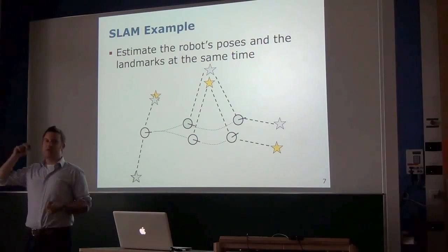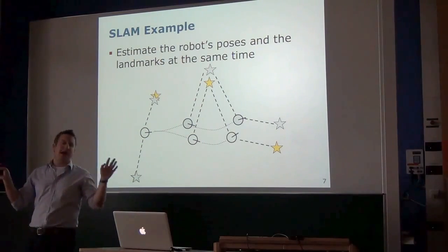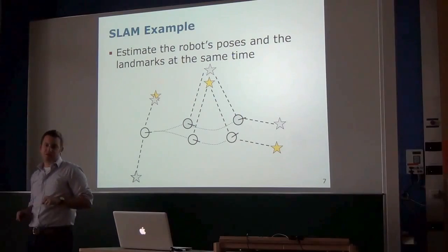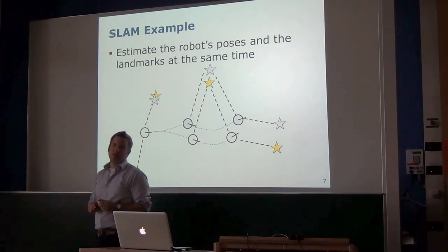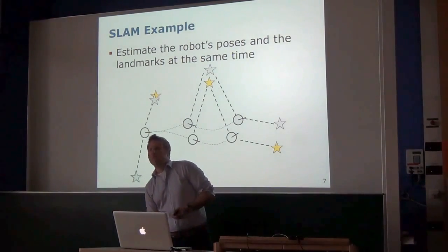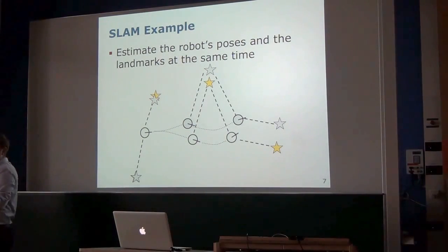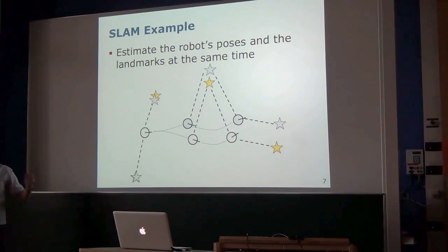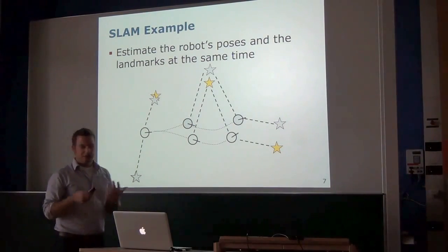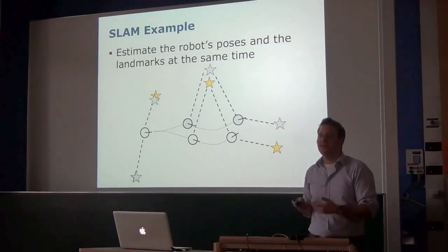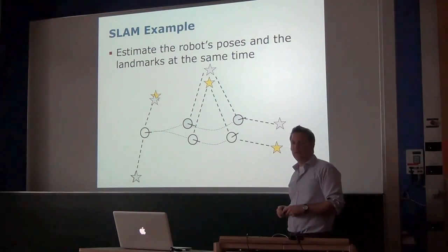And then you start the robot up somewhere in that map and say, okay, where am I? So you might see a tree here, a tree there, a tree there. It must be here, that location. So the 0, 0, 0 is the place you start and this distance from your position. I mean, this is kind of an implementation detail. Typically in a SLAM system, you start up the robot, it says I'm at 0, 0, 0, and it just starts. Because it's its own coordinate frame, there's nothing which needs to be there. You can also use 1, 1, 1, whatever you would like to have. So it's kind of just a convention of a reference frame.